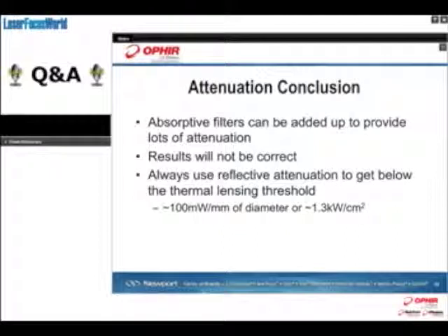Now, how do you make sure that you're parallel to the z-axis of the beam? Well, that again is generally a question of making sure that you're fixturing correctly, that you've got a good stage if you're trying to move through the beam caustic. Then you want to have a good stage that maintains the parallel nature. And then it's relatively easy to set that up and to check your parallelness by simply measuring the beam in a couple of positions.